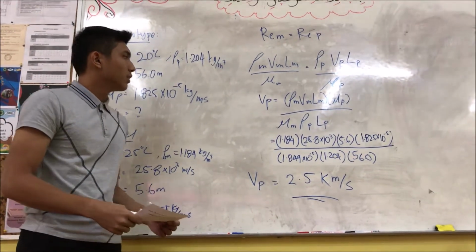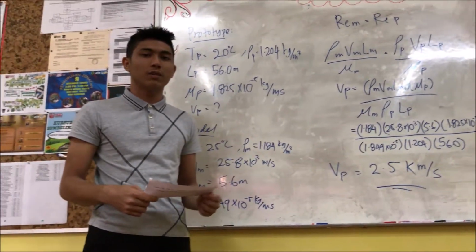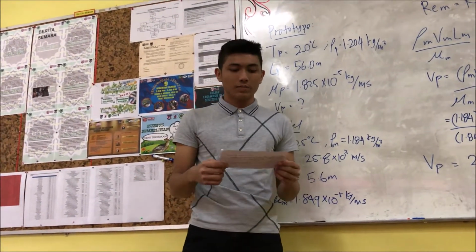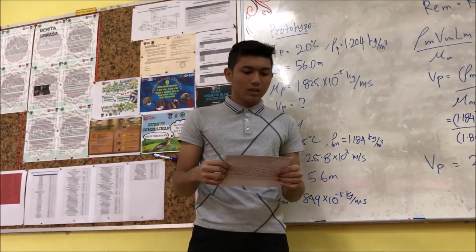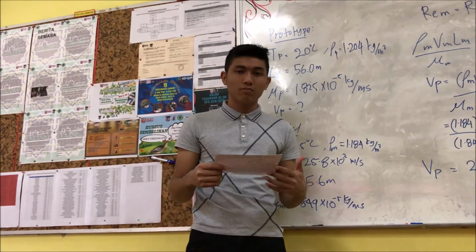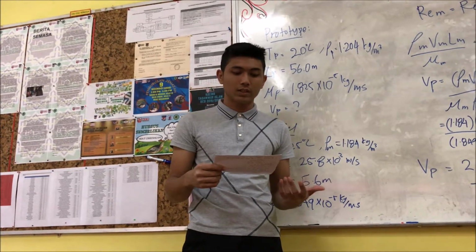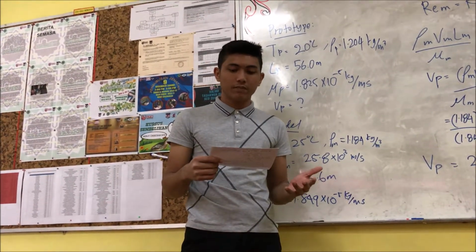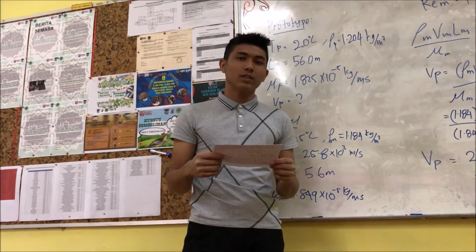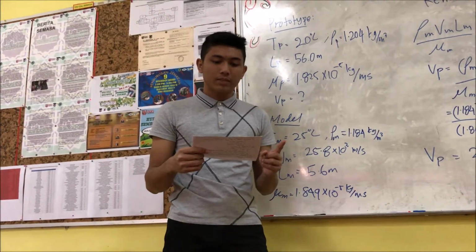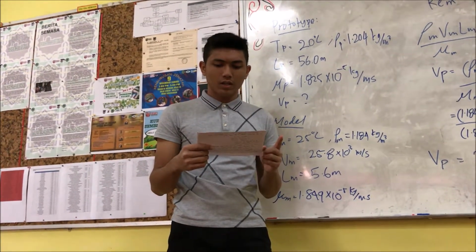So next, I'm going to explain about a method called the method of repeating variables. This method is used to generate the non-dimensional parameters. It is a step-by-step procedure or recipe for obtaining non-dimensional parameters. So the first step is to list the parameters in the problem,